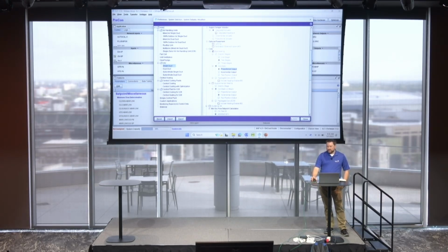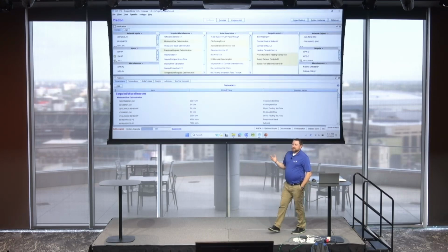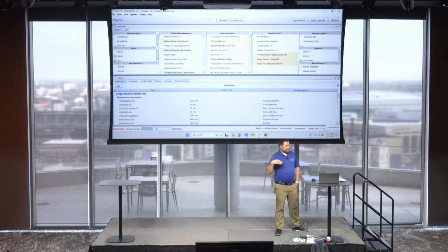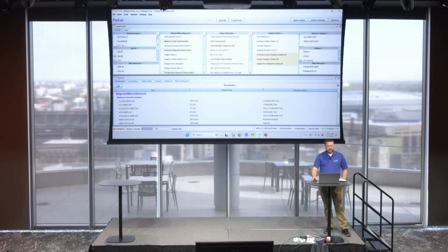If I save this, when I close, if I go and spin up that VAV program, that single duct application, now I have my predefined selections, because typically you're working with the same engineers, and 80, 90% of the time you're going to have the same selections, right? So there's no sense in having to select that each time. So that's kind of a nice little tip and trick for CCT. Again, that was settings, system selection.